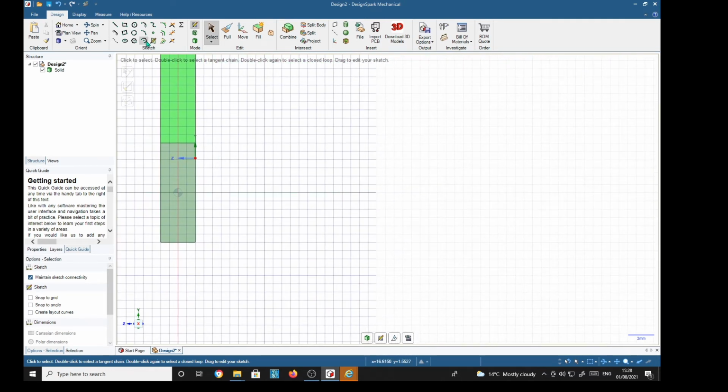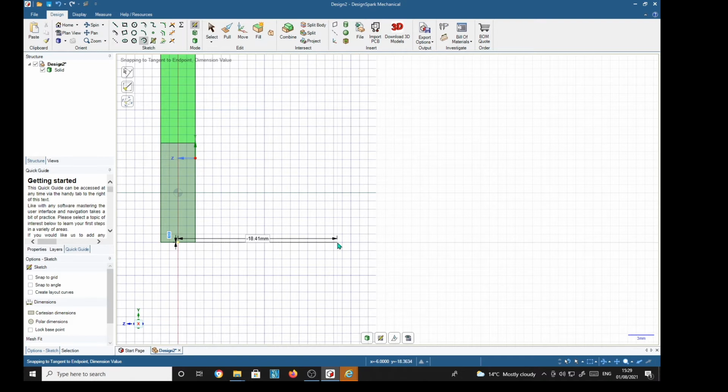And we'll use the sweep arc tool. We hover on the center of the blank, press the shift, and we get a temporary reference point. 0 is fine for the vertical, which is there, so we tab to the horizontal, make that minus 40. 40, yes. Click, and we can make our sweep arc.